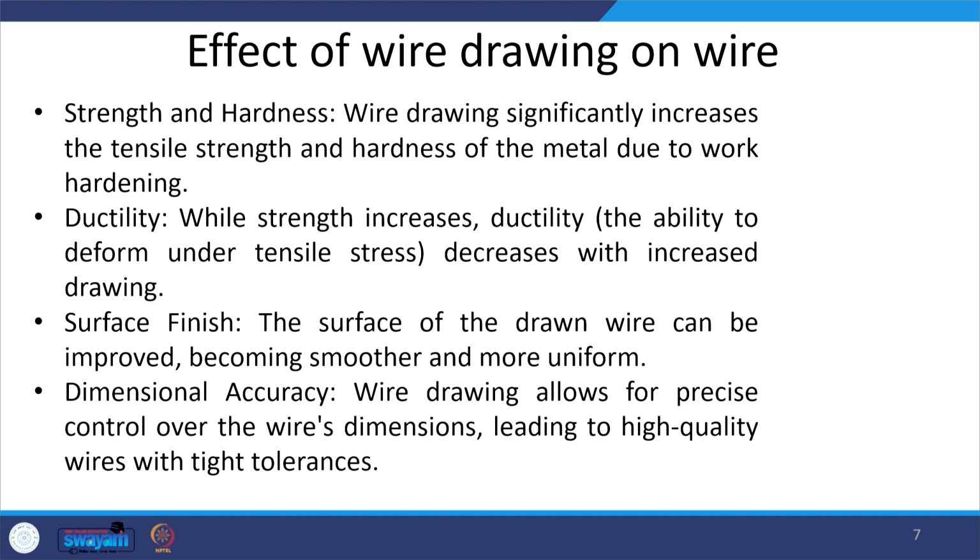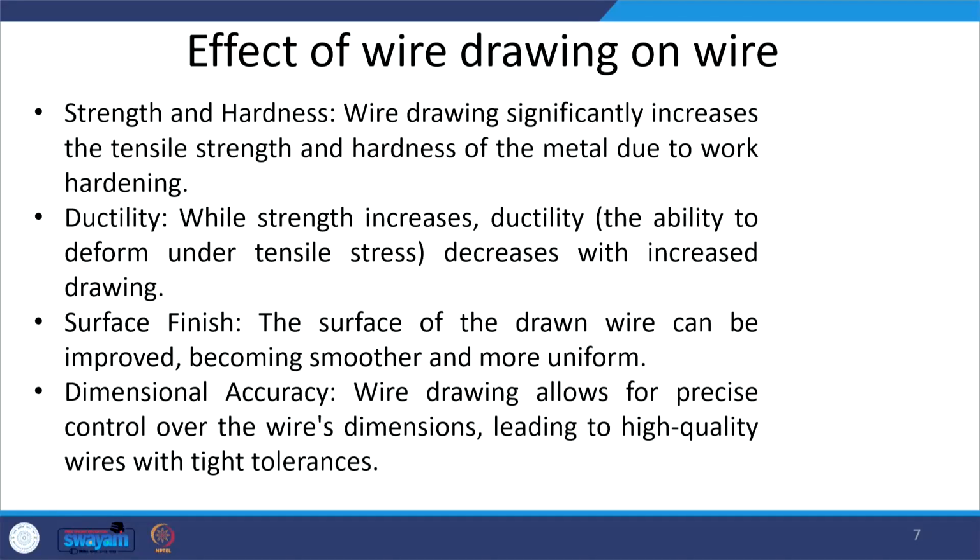can, in case of the multi pass wire drawing arrangement, we need to see that the material retains the enough ductility, and if it loses its ductility, then we may have to incorporate the in process annealing during this wire drawing process.